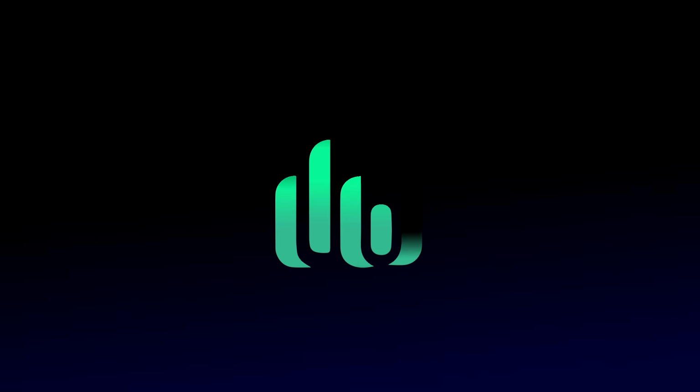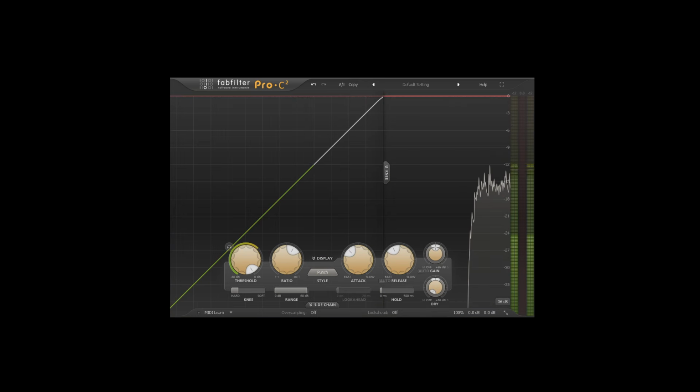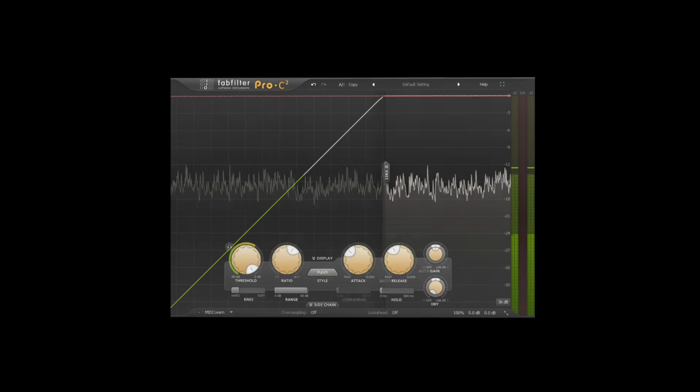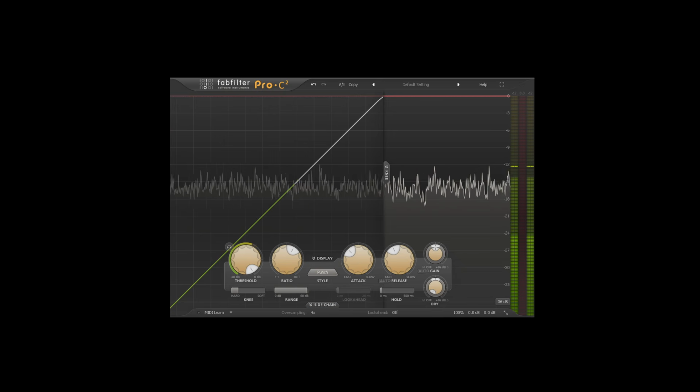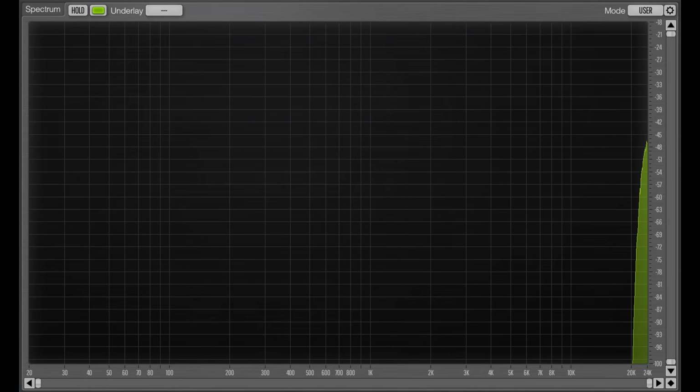With the quick proviso that this is only a viable option because the oversampling is linear phase. With minimum phase oversampling, any differences due to aliasing would likely be dwarfed by the huge phase differences, and we wouldn't learn anything. But let's double-check that with the control. Here's pink noise, running through an instance of C2 that's not doing anything at all. And the same noise through another instance with 4 times oversampling. Let's null them. And there's nothing left, apart from the expected differences right at the highest frequencies due to the anti-aliasing filters.